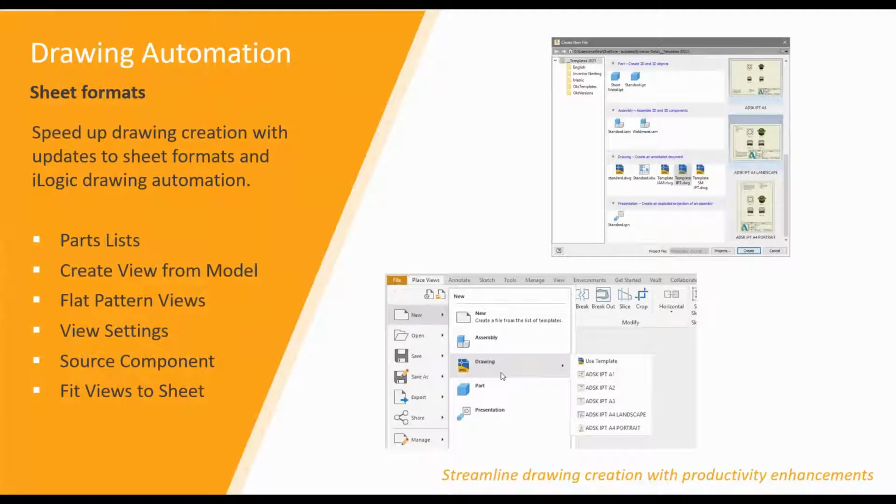automation of your drawing environment. So basically, when you create a new drawing sheet, a new sheet inherits the settings based on the originating sheet format. Now what's happened here is the settings for each placed view, that is shaded and unshaded. Basically what this 2021 software allows you to do is place your base view and your projected views and then define them as shaded or unshaded views.